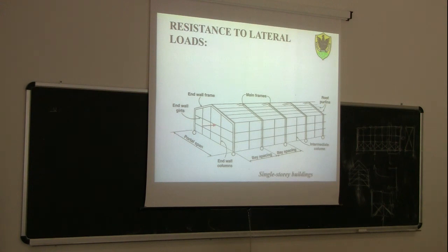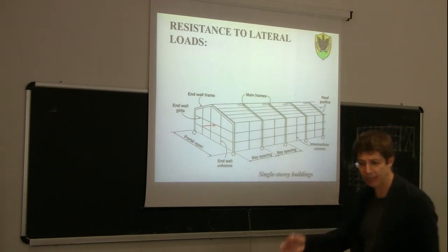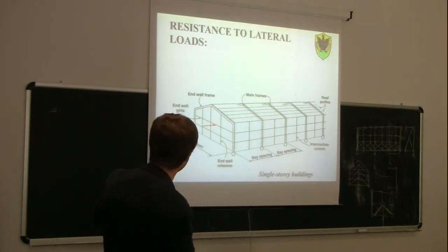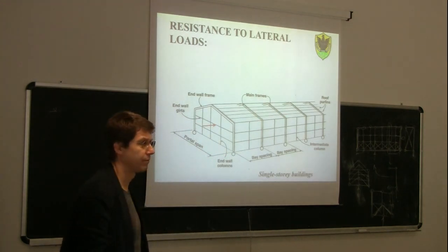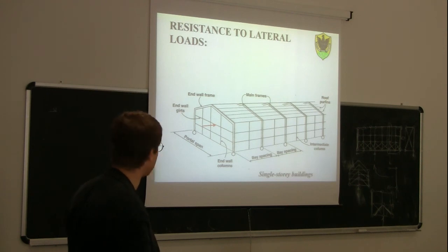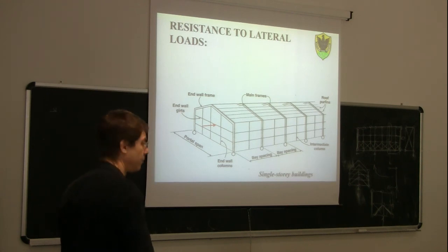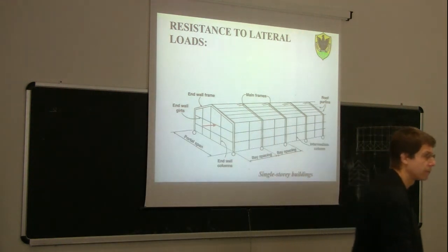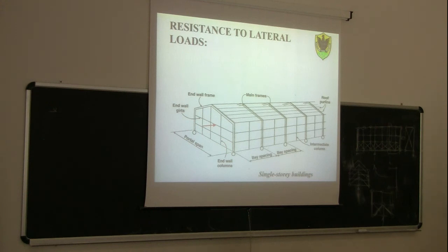Now, resistance to lateral load. What about the resistance of this building, which is made of in-plane stable frames, to a load applied out of plane? Is that stable? Can I transfer this load down to the foundation? And how can I transfer this load down to the foundation? Is it unstable? Are you sure it's unstable? Yes, because you see here there is a pin connection. I could make this system stable only if I was using a fixed connection here.